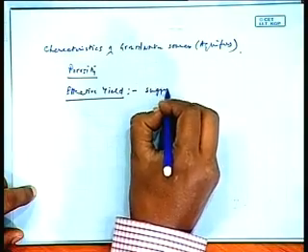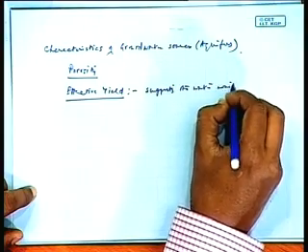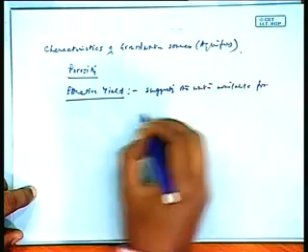So it takes about the specific yield. Even if the water content may be 20% or 30% of the volume, only the available water that can be drained out would be about 20% or so. That depends on a particular kind of structure. So in addition to porosity, we have another parameter known as effective yield. The effective yield suggests the water available for transportation.